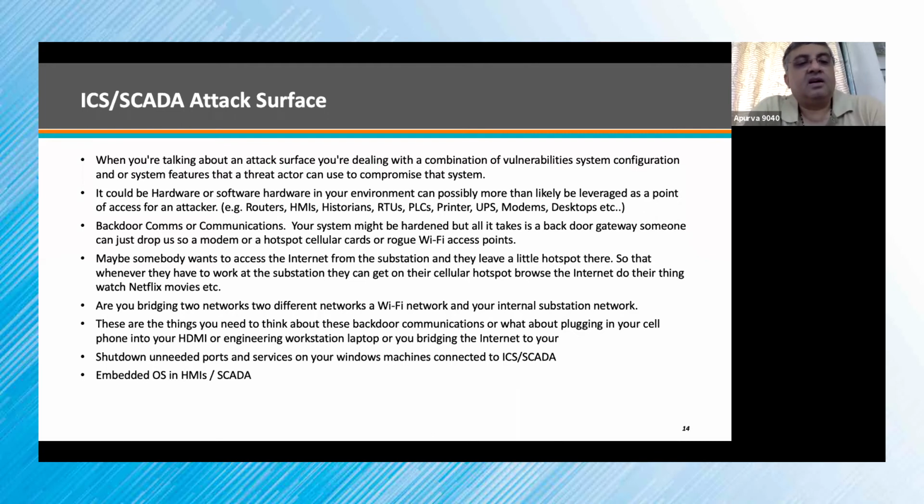Then there are connections to your SCADA through workstations. So you have to harden your workstations, because again, these workstations are nothing but Windows desktops or laptops. If you don't put the patches correctly, it will again impact your system.